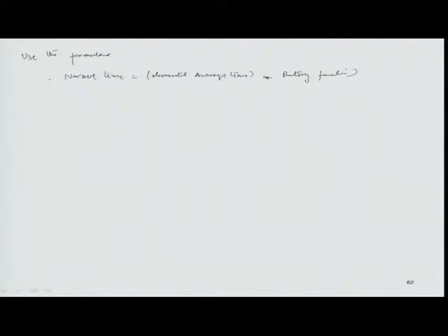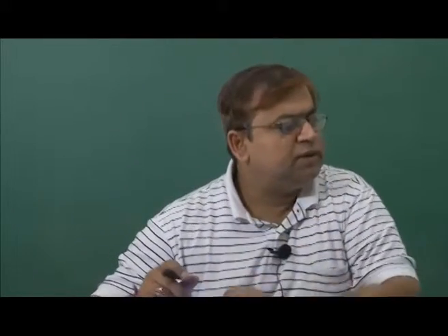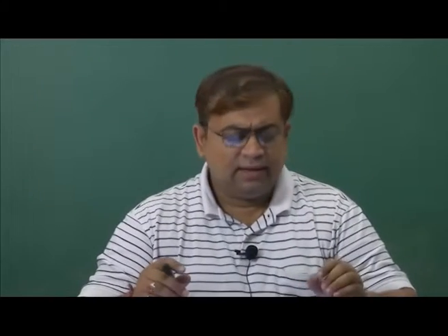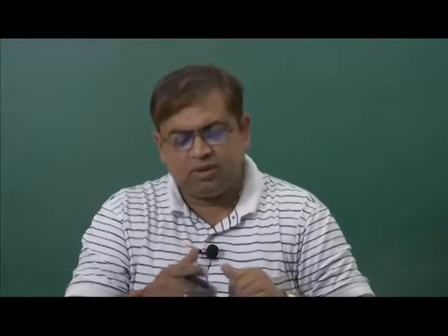Now, how we have arrived at the elemental average time is based on some of the techniques that I have earlier illustrated, maybe video filming or microfilming, and adding some time scales. I would like to mention that in the CMO chart example, we also talked about time units, about 1/2000th of a minute. It's a very small time unit, so essentially we are filming all the micro motions associated with such time units. When you do time studies or motion studies, there is always the question of the resolution, the minimum level at which you can record, so that you get more precision and accuracy in the whole process.